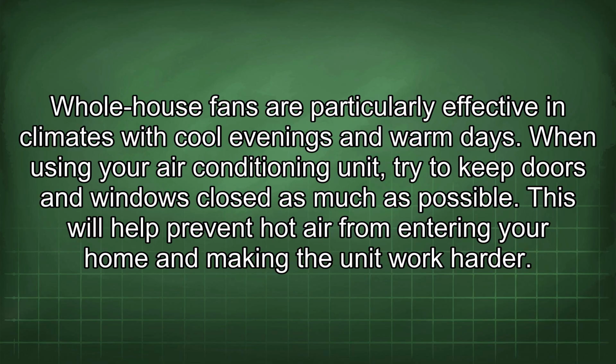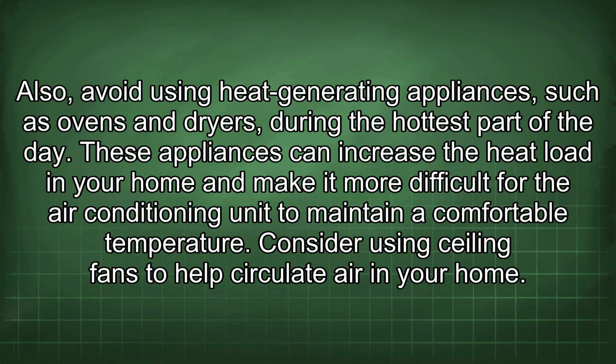Whole house fans are particularly effective in climates with cold evenings and warm days. When using your air conditioning unit, try to keep doors and windows closed as much as possible. This will help prevent hot air from entering your home and making the unit work harder. Also, avoid using heat-generating appliances, such as ovens and dryers, during the hottest part of the day.